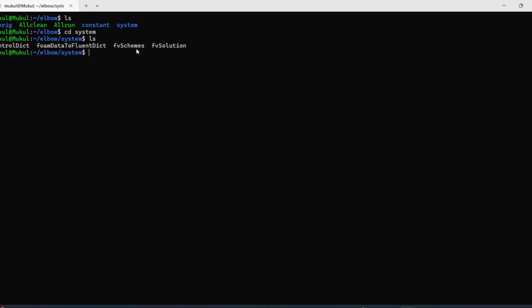if you have made a mesh in ANSYS Fluent, you can transfer that mesh to OpenFOAM by typing the command fluentMeshToFoam. You can convert the mesh data accordingly for OpenFOAM, and then you can run the solver, whatever solver you wanted to run.